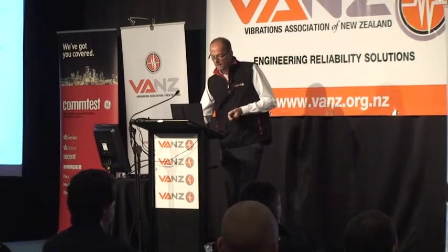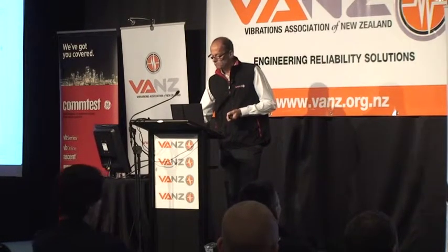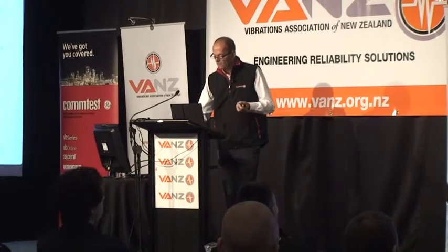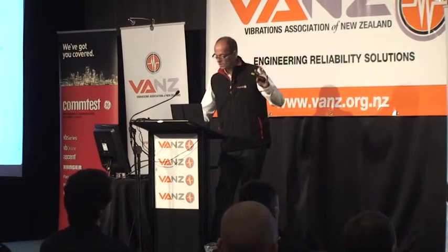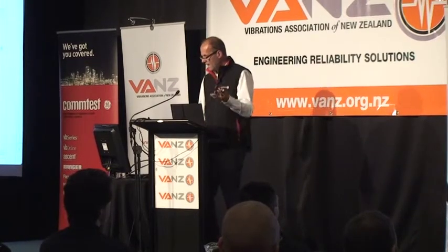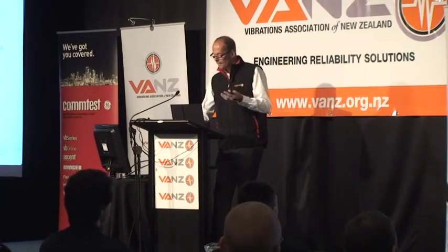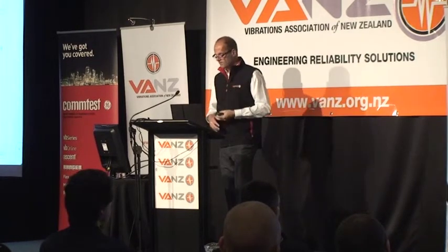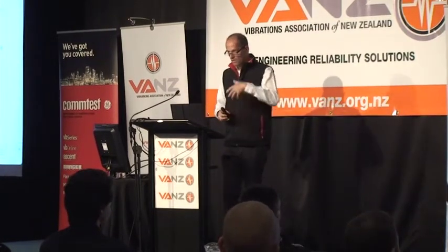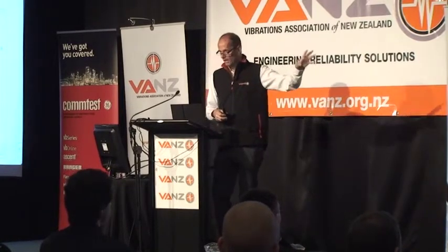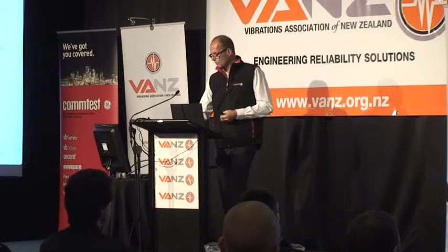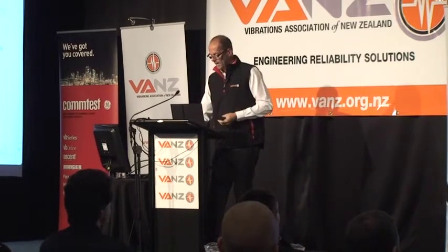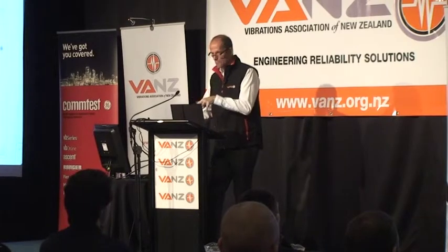And, if there was hardly any vibration from that source, we wouldn't see much vibration. Likewise from the bearings. We'll keep it real simple for now, but we've got green vibration from the bearings. And if the bearings were in tip-top condition, we wouldn't see any vibration at that frequency. But if there's more of a problem with the bearings, then we get more vibration. Bearings generate a few frequencies, and it's a bit more complicated than this. The point is, though, that what we actually measure is a combination of all 3, and it all sums together to make that more complicated.